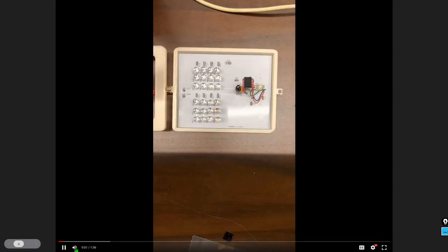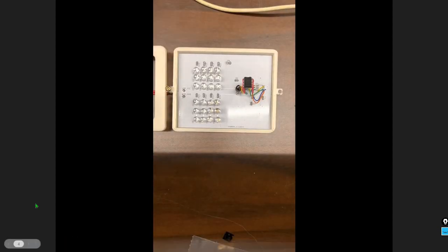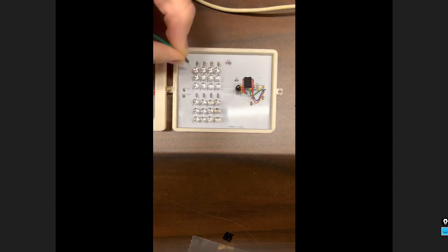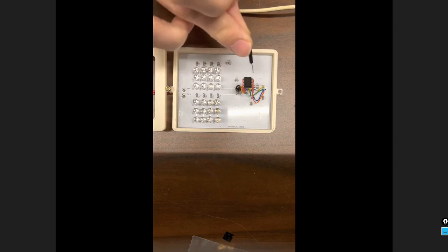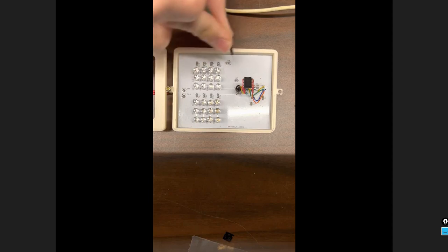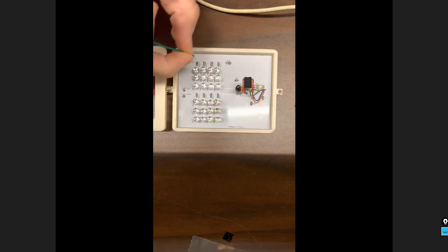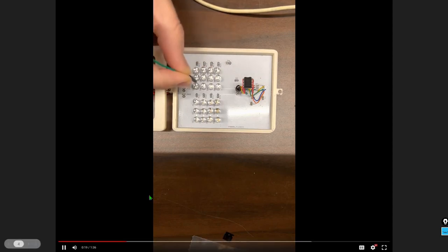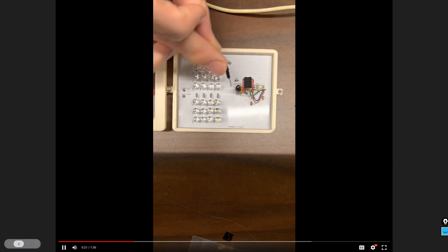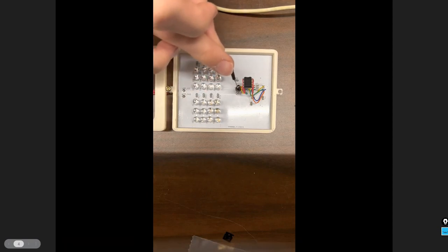Here we have the design for our precision landing beacon. Right here, the voltage is sourced from a 9-volt battery and is connected over to these resistors as well as the supply voltage for the timer. The current's then collected down from here past the resistors into the first of each column of the array and is collected into the collector of the transistor right here.